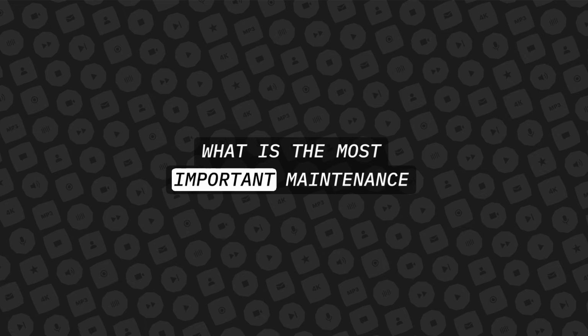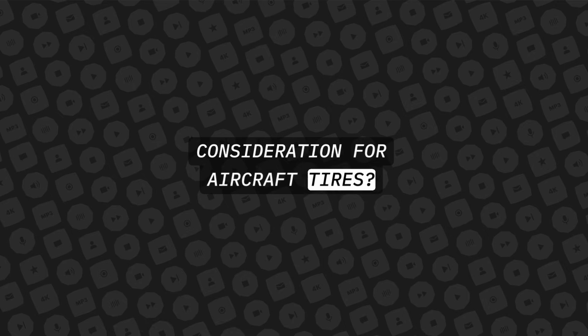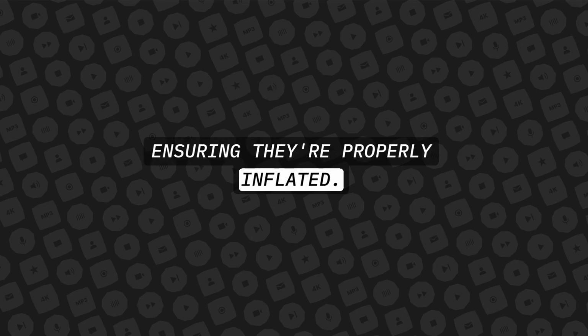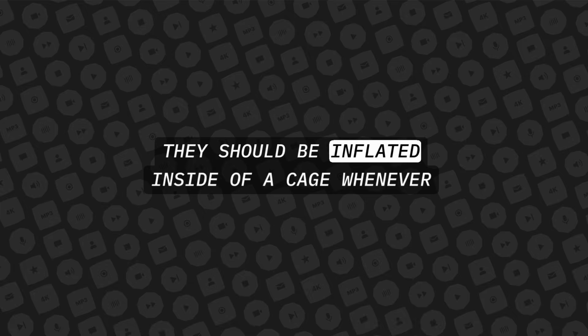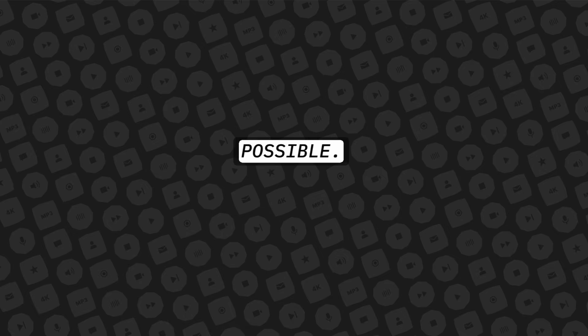What is the most important maintenance consideration for aircraft tires? Ensuring they are properly inflated. What safety procedures should be followed when inflating tires in general? They should be inflated inside of a cage whenever possible.